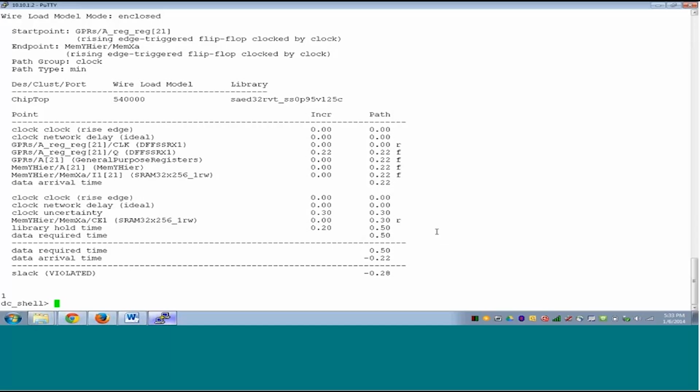You'll see a lot more of this in unit 5. Please note that for hold timing, you should not be concerned about the hold timing in synthesis reports. In most of the cases, there are very special cases where you should worry about the hold timing. But as a thumb rule, after synthesis, check the area, check the report constraints minus all violators, and if you see violations, analyze the setup paths. Forget about the hold paths for now.